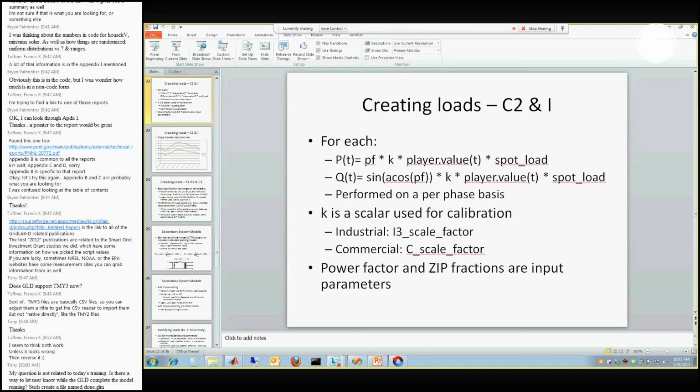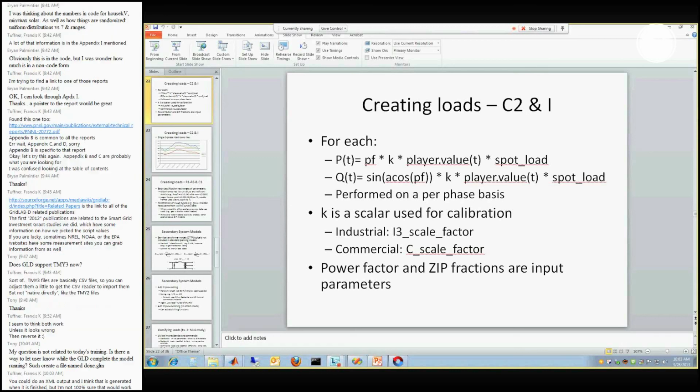We're also looking for flicker. Is there a percent change that you consider to be noticeable? That's a good question. The only official stuff that I know of came out of GE probably about 15, 20 years ago. They created a flicker chart, and I have a copy of it somewhere. I can dig it up.